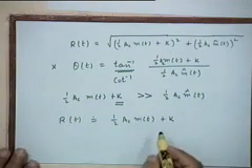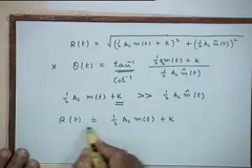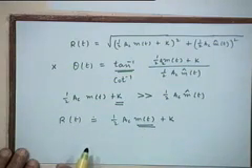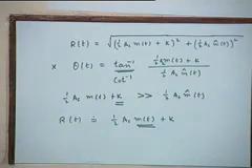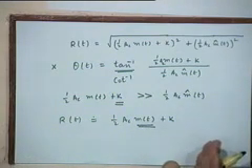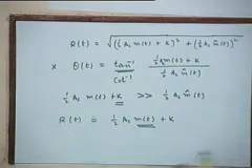And therefore if you ignore this constant, we got an envelope which is proportional to the message signal m(t), right? And therefore our envelope detector in that condition would produce an output proportional to m(t). You agree with that? If the envelope follows the message, the envelope detector obviously would produce an output which is proportional to the envelope. Yes, please.